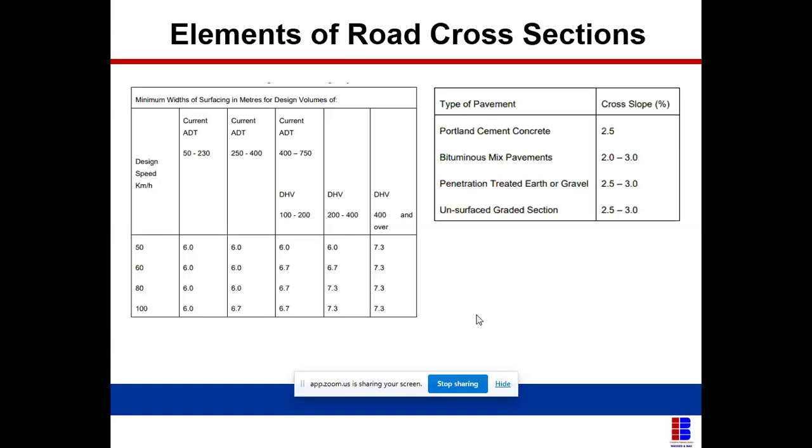Like now, let's say Abuja is busy like this, some areas in Abuja, and I know that we'll have tippers plying that road more. I can't design that road to have a gradient more than 4% or 5%. Because if the gradient is more than 4%, 5% or 8%, the thickness of that road will be more. If a trailer is climbing that road and applying his brake, there's every tendency that the tipper can slide back and fall back down. So those are the things we'll be looking at for the gradient.